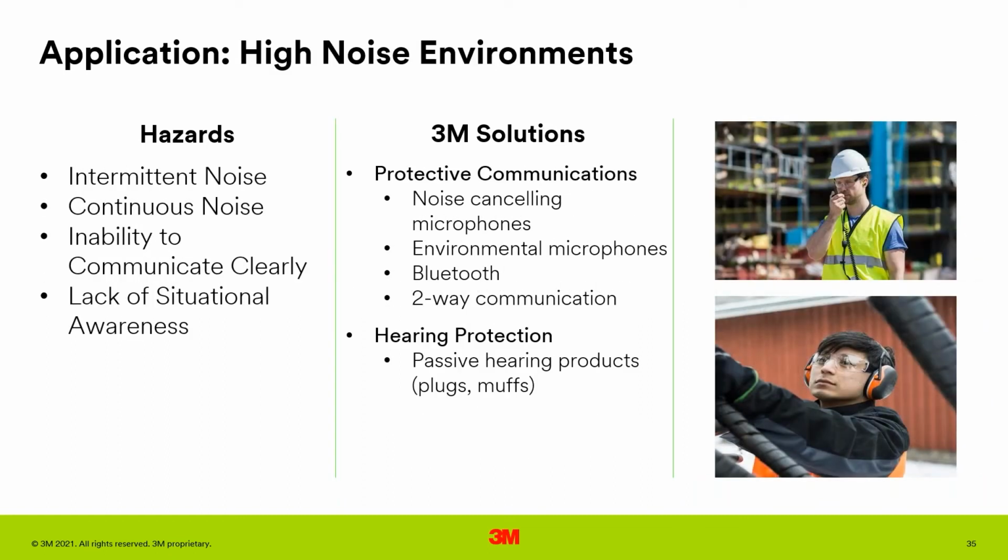So when you're thinking about high noise environments, you certainly have intermittent noise, continuous noise, and not being able to communicate, but there's also another thing that you have to be concerned about, and this is the concept of situational awareness. One of the largest hazards on a construction site, especially if you're visiting a road site, is being hit by equipment that's on the site. There are a lot of times backup alarms, but if you can't hear them, then you have a risk of being hit.